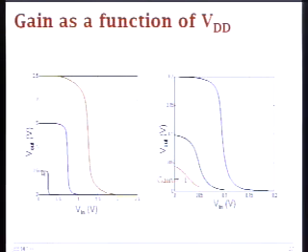What happens here when you keep scaling your supply voltage? Are you still in velocity saturation? Or are you in regular saturation mode? You are in regular, that's right. So when you're in regular saturation mode, you have more current, you have more gain, and then your curve looks nicer.